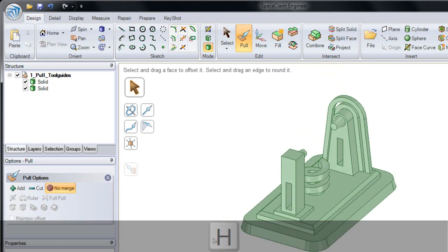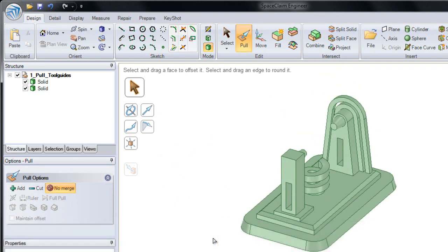So in this section, use our tool guides of Sweep, Revolve, and Draft to make 2 sweeps along our angled protrusion. Use Revolve to make a helical solid, making sure to check the No Merge option, and then draft some of the side faces.